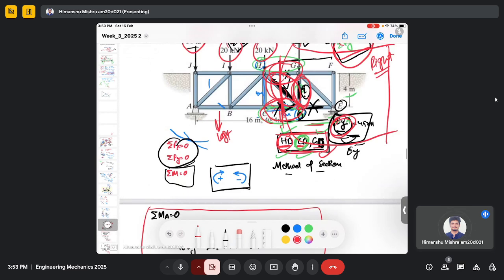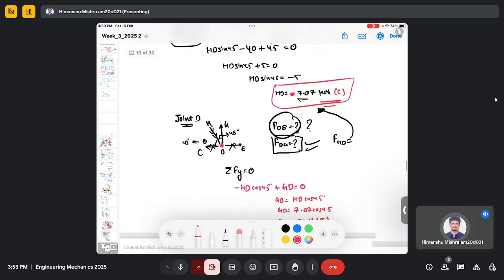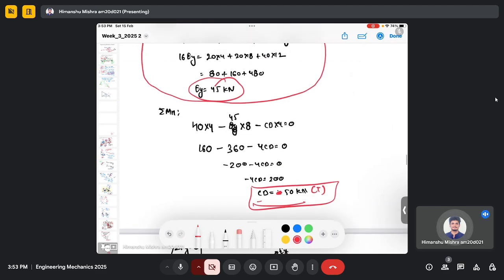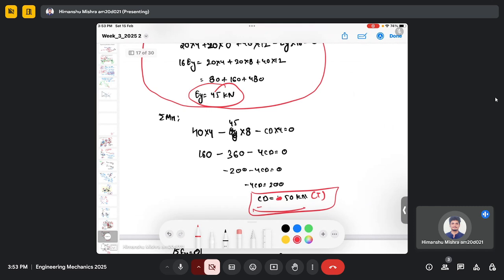So we actually select point D and then we do the usual procedure where we make a free body diagram and we use equilibrium equation to calculate the force in GD. So this you have to actually think, because once you cut the truss, there are a number of ways you can actually find the force in the unknown members, and that you have to decide how to do. You can use the moment equation. You can check if you can do the force balance analysis in the y direction or in the x direction in one specific part of the truss.